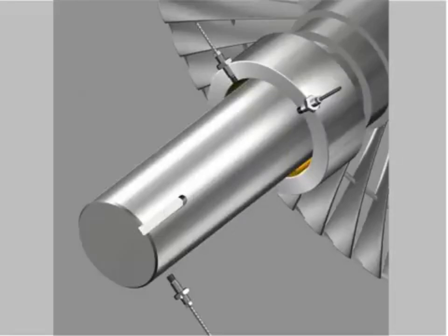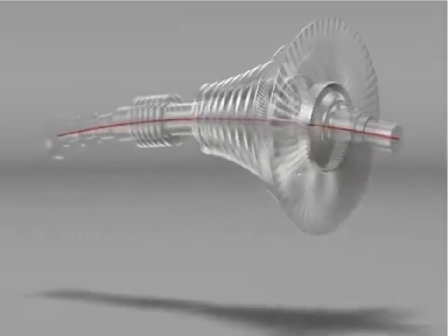And with this timing information and these two probes, we can tell exactly what's happening with the rotor, where it is inside the bearing, which is really important, and is it moving in a circular motion, a large circular motion due to unbalance, a small circular motion because it's properly balanced. Is it elliptical and highly elliptical because of preload from misalignment or something like that? There's so much we can tell.